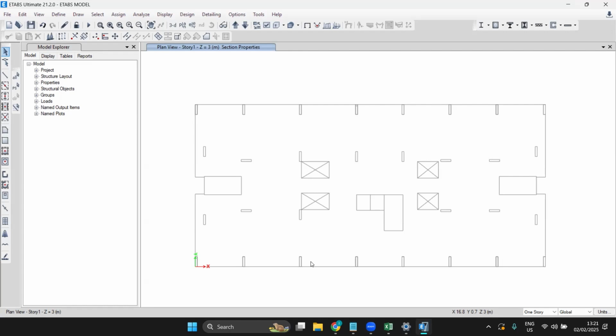I don't know, somewhere you missed something, but I don't know what it is. If you do it a couple of times, you'll automatically find where you made a mistake and can easily fix it. I'll tell you where you might have missed it. When you went to import the DXF file, in the beam, instead of selecting DXF, you might have selected a joint or slab somewhere. You need to select DXF under the beam. I know, I was not getting the layer thing.